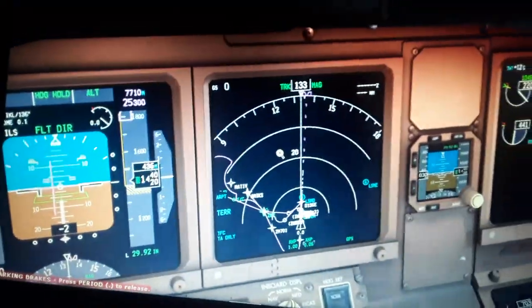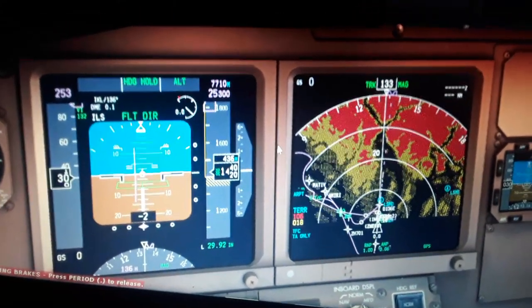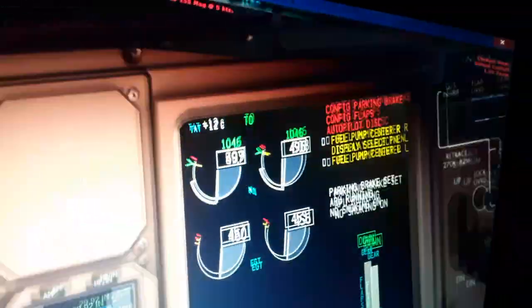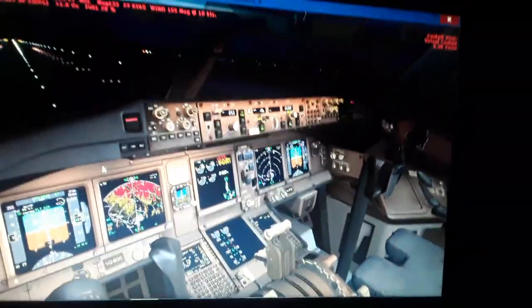For this display you will see a different terrain scan radar. Also you can see the airspeeds, everything is set, the LNAV, the flaps, and the horizontal trim here, the stabilizer before takeoff. So we advance the thrust levers for takeoff. We have the warning because we have the parking brakes on. So this is the outside view where we are and where we're going now. So we have a better view like this for takeoff. Cancel the parking brakes and go full takeoff, go out.